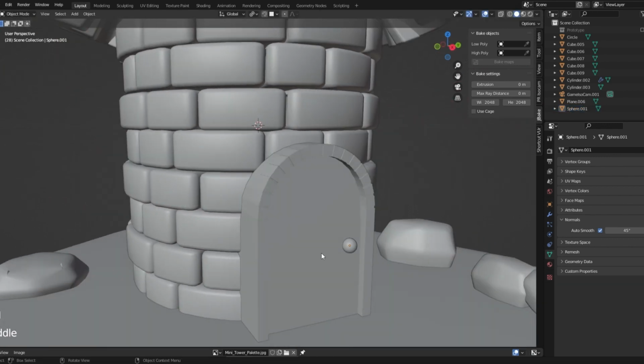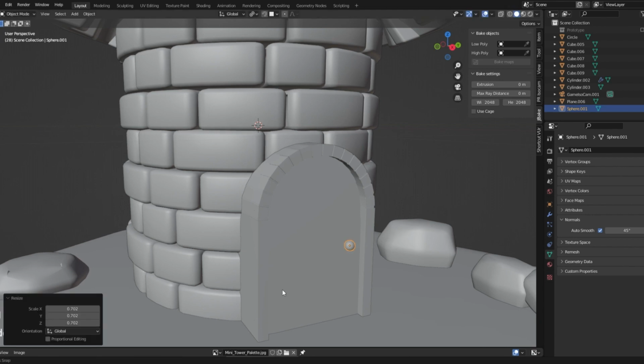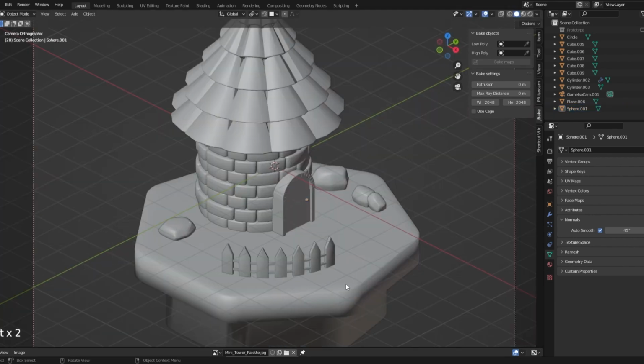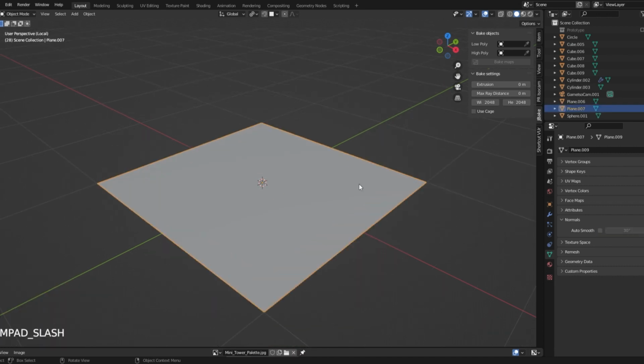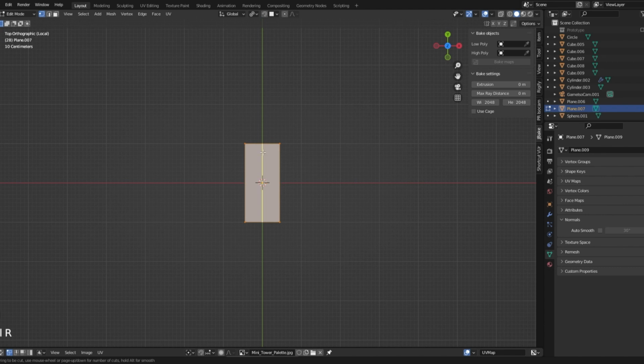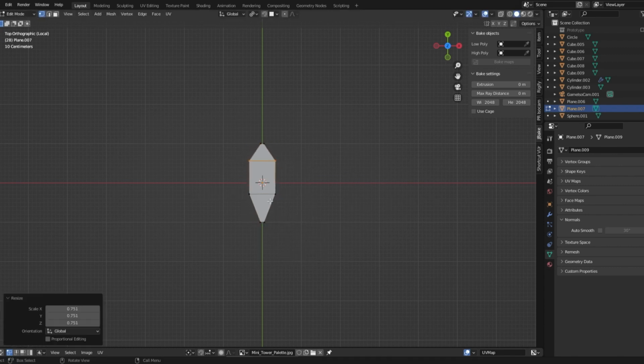Lastly, before adding the materials and the lighting, we're gonna make some leaves for more decoration. So we Shift A to add a plane, go to Top View, scale on the X-axis, go to Edit mode and Ctrl R to add some more loops. Scale them down to give it a somewhat basic leaf shape.